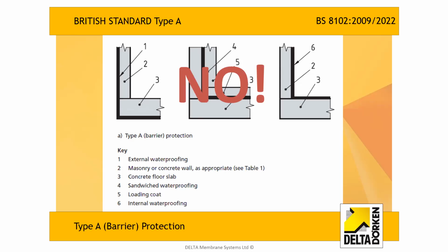it's a penetration, isn't it? Every wall tie is a penetration. The fact that pressure, when it comes through a structure and comes through what we call the negative side, is very powerful. It can force membranes off, and that kind of system is inaccessible for repair or maintenance, and there's no scope for testing during construction, is there?